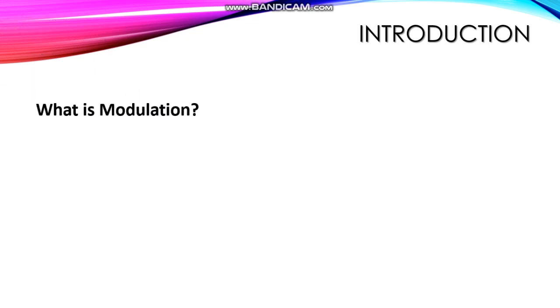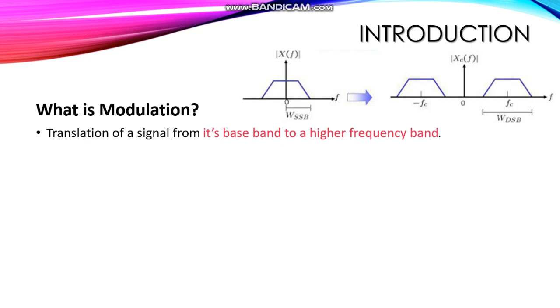For an example, suppose we have n number of signals which have same frequencies. So we can modulate each signal to a unique and different frequency band in the channel, then we can send all the signals over that channel without any interference. Basically what it does is, it translates baseband signals into bandpass signals. You can see in the image the result after modulation done.